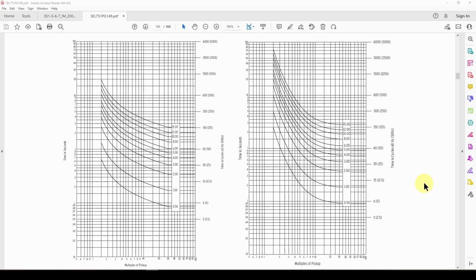So we said that one of the functions of the overcurrent relay is, once it has determined that the current is above a normal value, to figure out how much time to wait before it actually trips the circuit breaker. And that depends on how much current. Again, I encourage you to look at the fuse video where we explain these inverse characteristics.